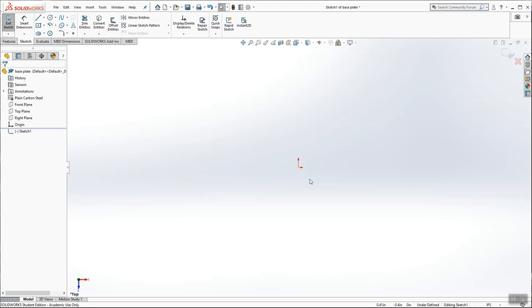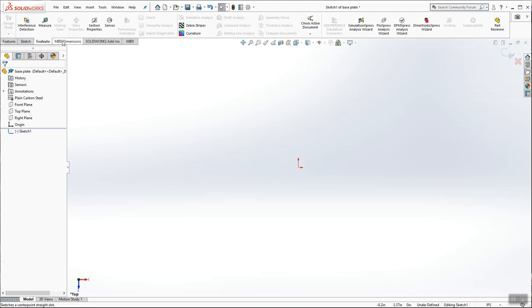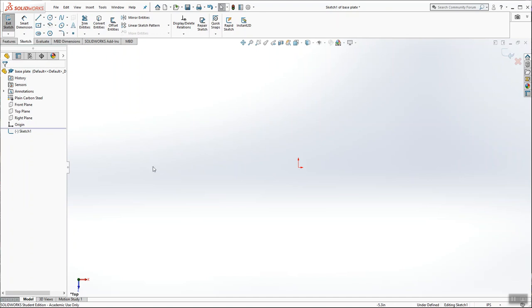And how I want to start drawing the base plate is with the 2.2 inch diameter circle. So now that my sketch toolbar is lit up, and if you're on the wrong toolbar, you can just click on them. But when you begin a new sketch, SolidWorks will automatically light up the sketch toolbar for you. You'll also notice that there is a red X and a finish button icon in the upper right hand corner. So we know that we're working inside of a sketch right now. So we've chosen the top plane. Now we have to draw something.